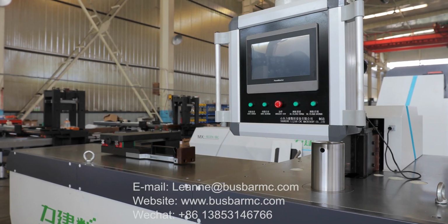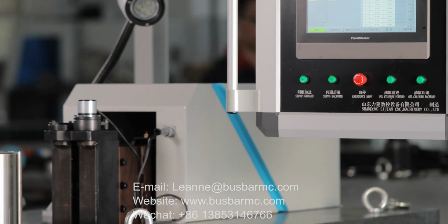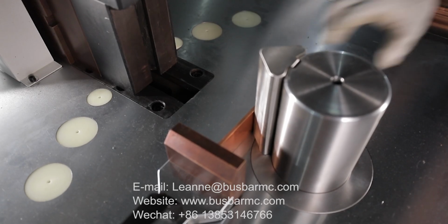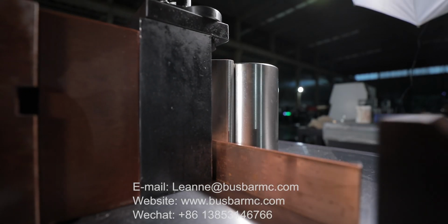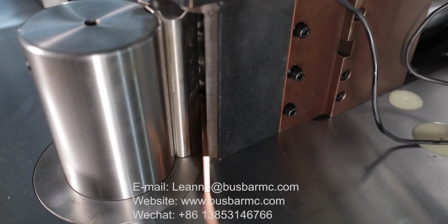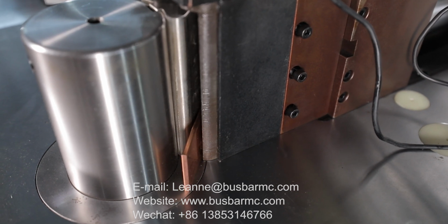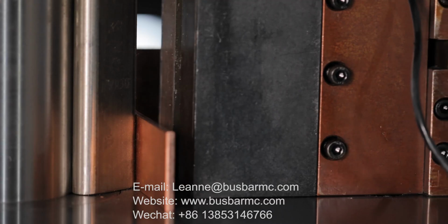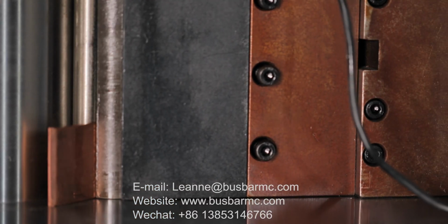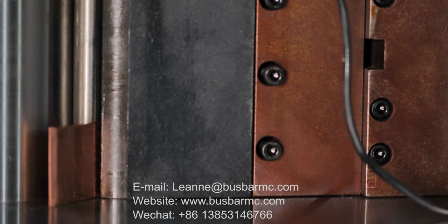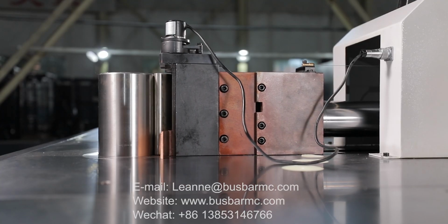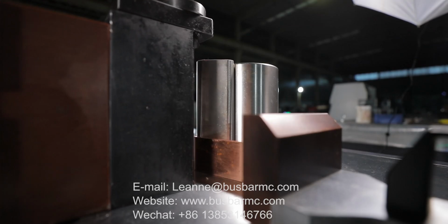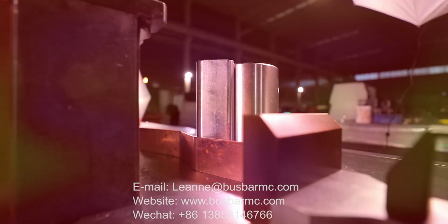The structure of the machine adopts an upper open type, which can conveniently take and place bus bars, and the bending power is supplied by double pumps to ensure bending efficiency and bending precision of the machine. The gauge of the machine is servo controlled and the position can be adjusted manually according to the needs, which can easily realize the control of the position of the bus bars during the work of flat bending and vertical bending. The machine also can be equipped with an electronic die system that detects bus bar bounce according to customer requirements.